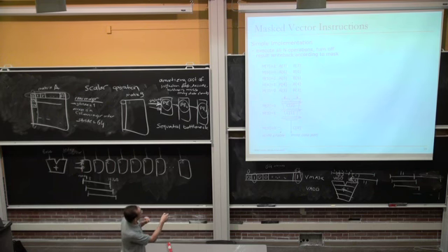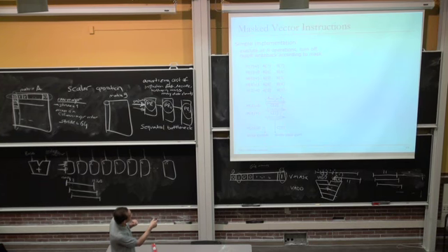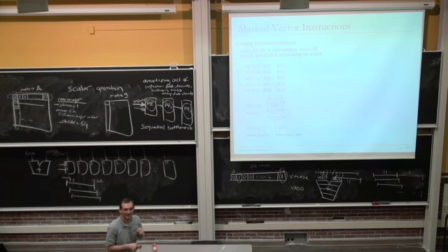So in addition to the data elements coming into your adder, you also have the mask bits, and the mask bits basically write enable your destination register. This is one implementation. It's inefficient because what if a lot of your mask bits are 0? Then you're doing a lot of these adds for no reason, just to drop them in the end.